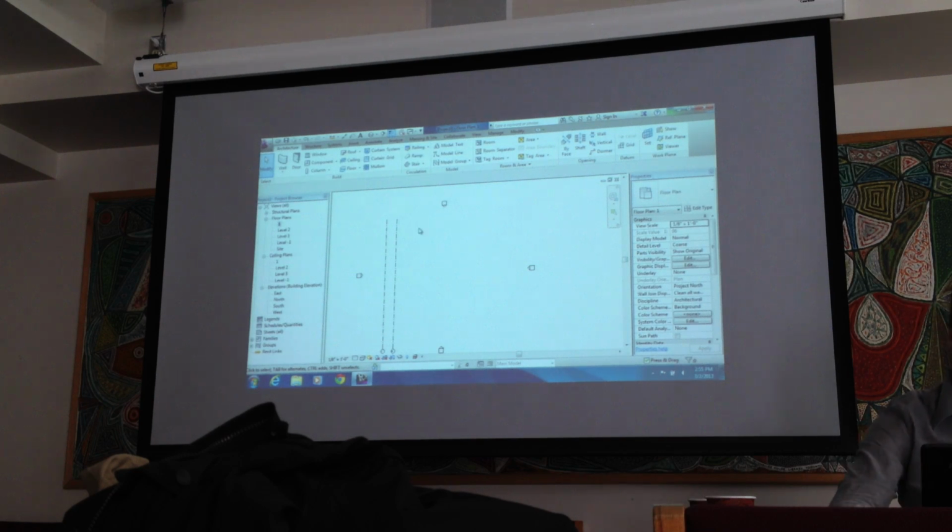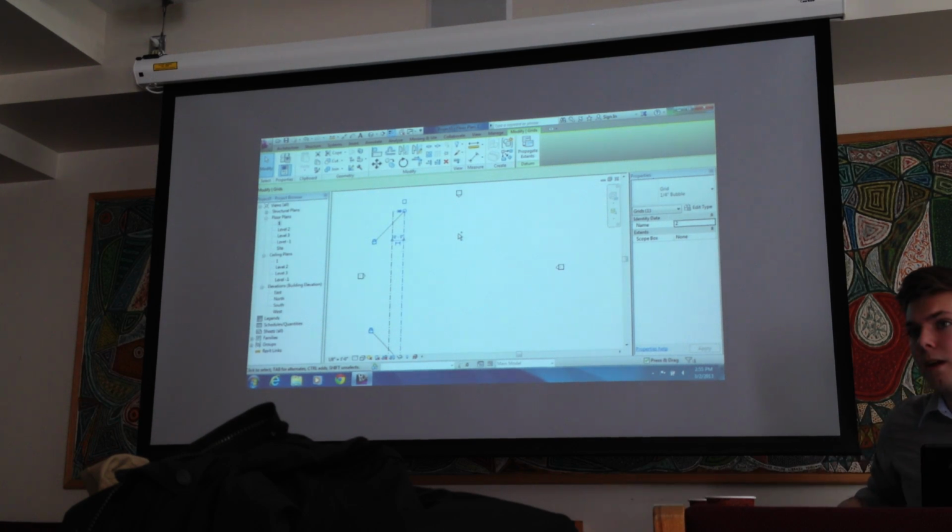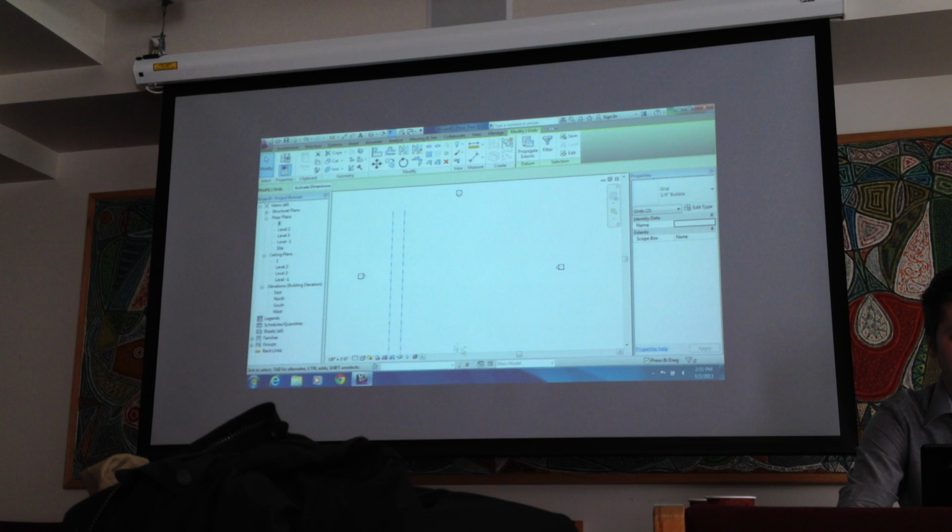far. You can click both of them, and to click both items, or if you want to subtract an item after you click it, you use the Shift and Control tool. So if you click Control, you'll see how there's a plus sign next to the mouse. So that means you're able to select more than one object. Or if you select a numerous set of objects and you want to add a few individual objects, you hold Control and you're allowed to click other objects like that.